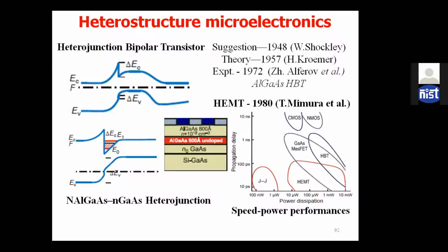Here, if you see a heterojunction HBT as compared to a normal BJT homojunction, the transport property is quite far better as compared to the homojunction. Similarly, as explained, the heterojunction by taking AlGaAs and GaAs. It was reported that if we use this heterostructure property, then we can drastically improve the transport property.